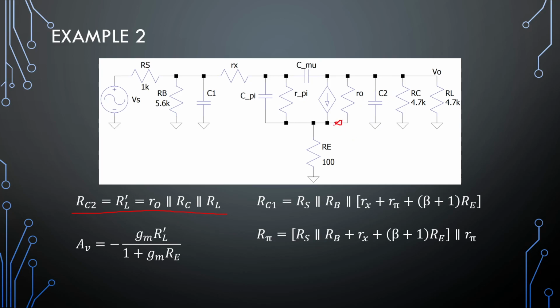Since we typically see this as a virtual ground, other people will say, if you go deeper into electronics, it is this resistor plus the gain of this amplifier multiplied by this resistor in parallel with R pi, and it's a lot of maths. What it says in the end of the day is that what is sitting here is just a big impedance, so it would actually be better just to use RC parallel with R load in those cases.